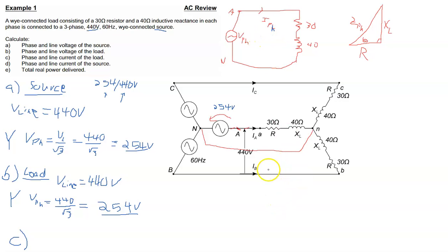In any event, if we're considering a line, Z line is not something down here that really we consider. So we got a 30 and a 40 with an angle in between them, theta L. We got another 30 and a 40 over there, and if we're going to try to add them together, remember there's a 120-degree angle right there, and so Z line is half complicated, and so really it is Z phase that you want to do, and that comes from this impedance triangle right here, right?